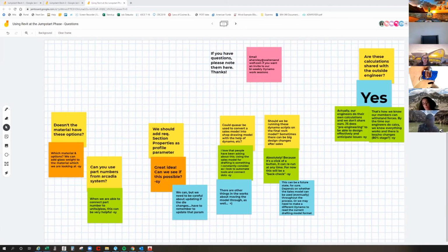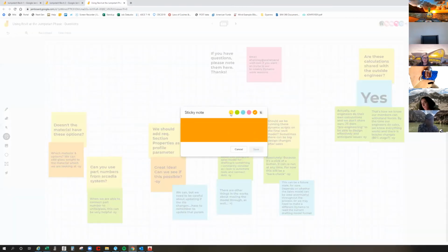When we build that profile, we'll decide which part property we have to use, which IXX of the part we have to use for that profile. So once it is entered into the profile itself, when you extract the data from the profile, you can extract the IXX value that has been used for that profile.